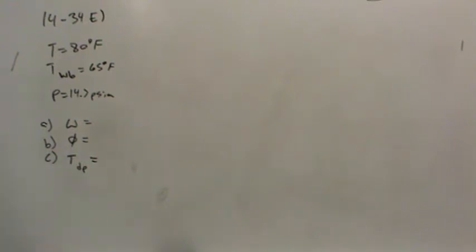I know what numbers I think they are. What do you think? One thing that may help, you can just make a mark at the state point once you find it, the intersection of the dry bulb and wet bulb temperatures. That might make it easier to use your piece of paper to pivot around and find all the pieces of information we need.